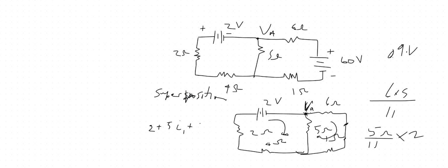You did a voltage divider, which means that if this was R1, R2, and R3, the voltage across R3 is VA, which we're looking for, right? So we'd have to say VA equals R3 over R2 plus R1 plus R3, right?